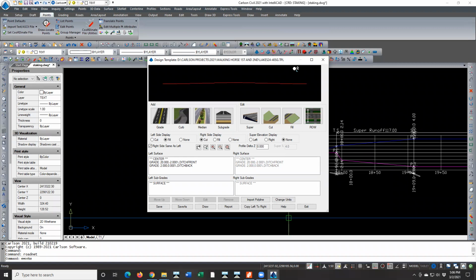All right, so this template then, when you process this, is going to go out there and try to grade this surface in, which would be what you would ultimately cut down to start building your road. Is that correct? You're at the bottom of all of your subgrades at this point? Okay. And so when I slope stake, they want everything to basically to the back of that ditch. Okay.